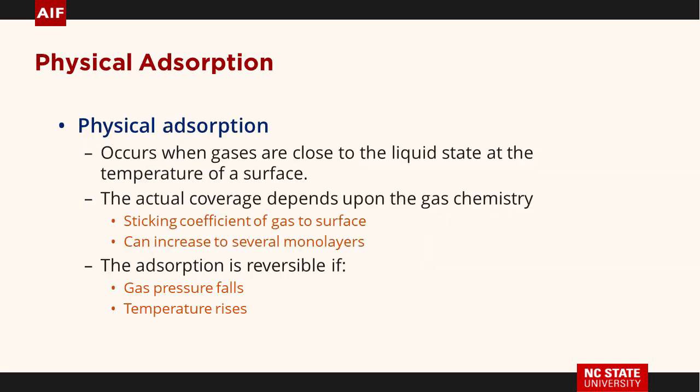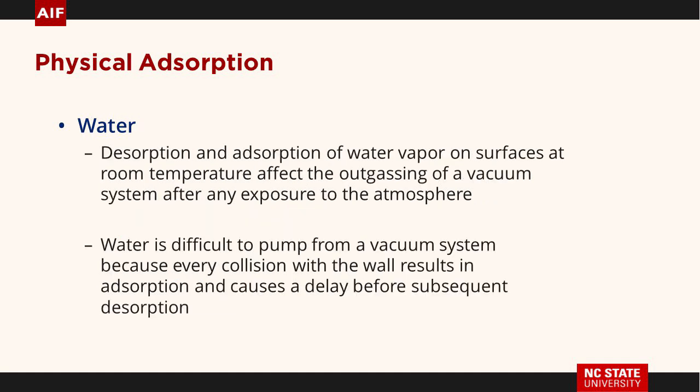Physical absorption occurs when the gases are close to the liquid state. Here we're mentioning the sticking coefficient of the gas to the surface. It's not always 1. It can be a lot less than that. Remember I said at 10 to the minus 6 torr, 2 seconds and you're going to cover the surface. What's our real problem? Water. Yes, we do live in North Carolina. It's usually humid. We haven't had as much rain. But if you open your chamber to air, all that water gets in.